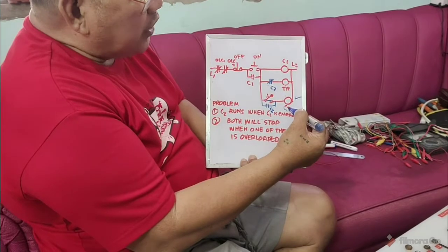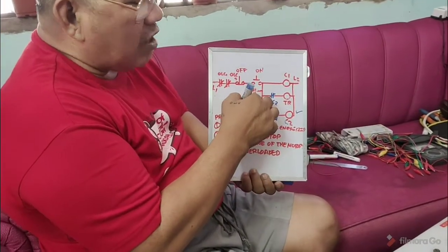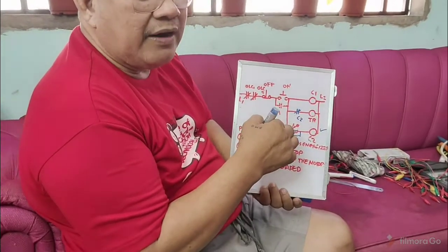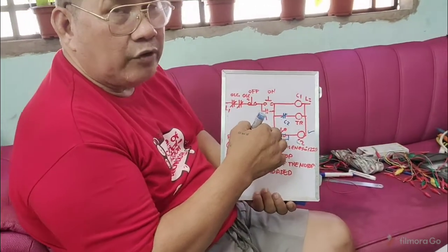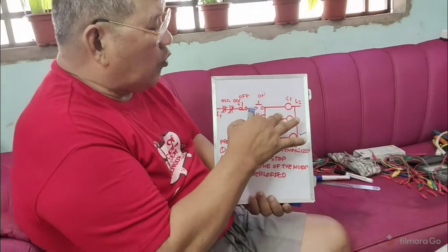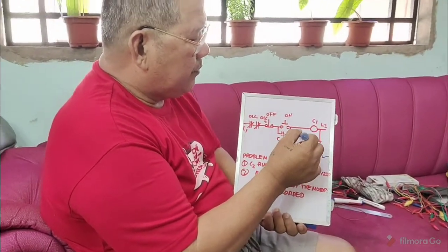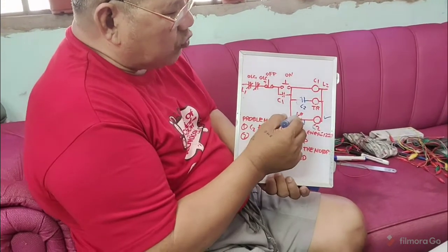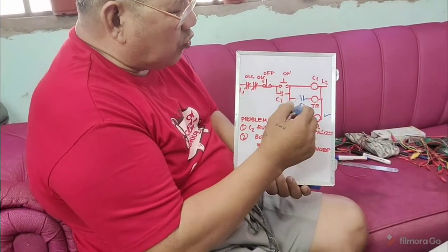When the conveyor 2 is energized, of course, what will happen to the auxiliary contact connected in series with the time delay relay holding coil? This will also open. So when this is open, what will happen to the contact here? It will go back to normal position.